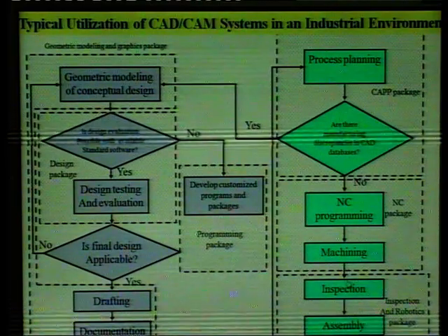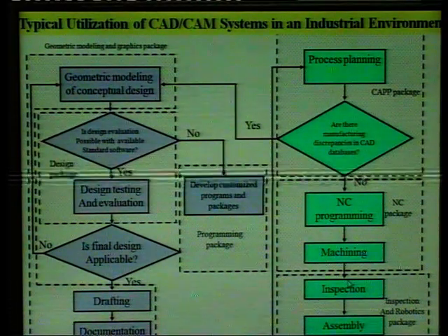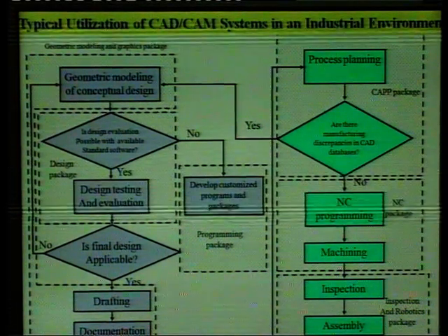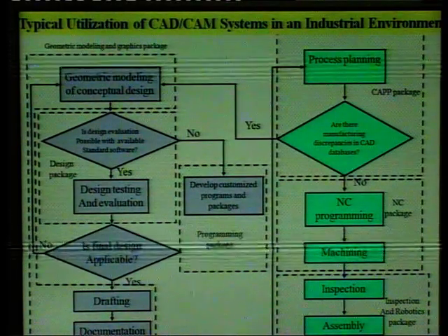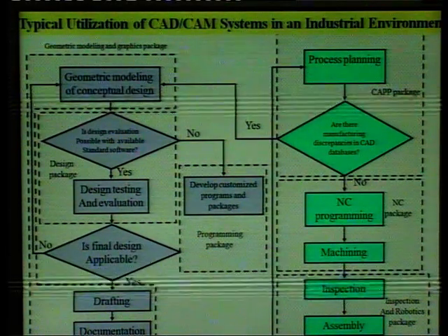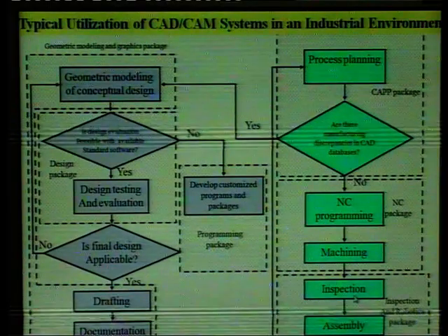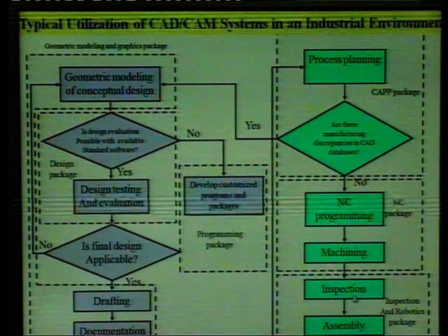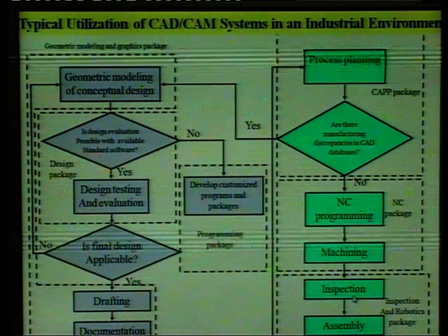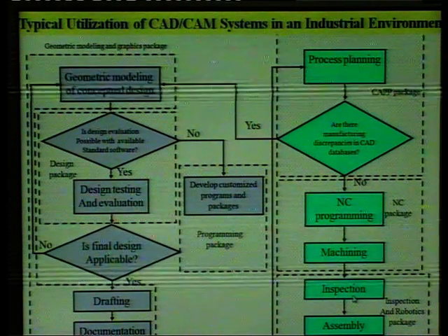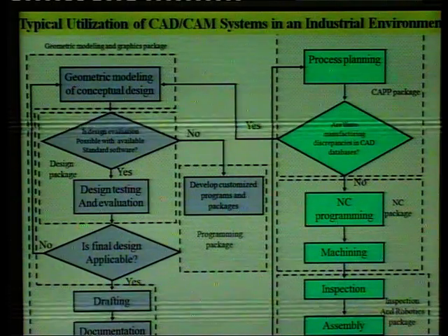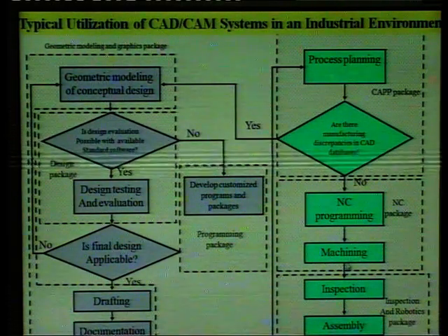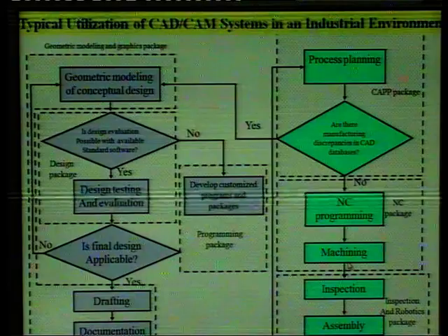Inspection can be of two types. Again, discussing more on the topic of inspection is beyond the scope of this particular lecture, but still it would be pertinent to mention here that inspection could be online inspection, or it could be a sampling inspection. If it is online inspection, then it becomes part of the machining, and it is conducted on each and every part.